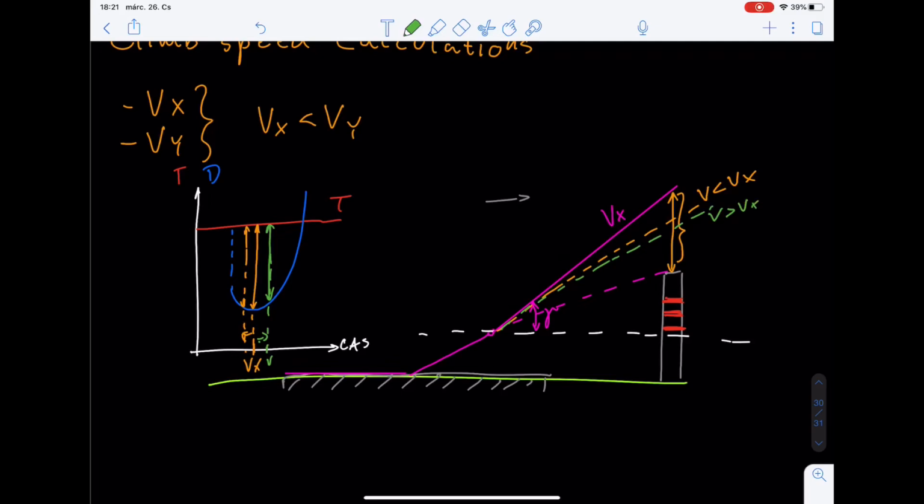And again, we see a reduction in the flight path angle, so therefore the obstacle clearance, the vertical distance between the highest point of the obstacle and the flight path, is going to reduce. So it's visible that I get the best obstacle separation by using the Vx, the speed for the best angle of climb.